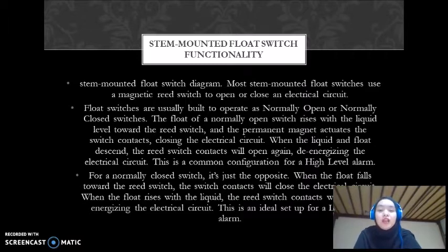For a normally closed switch, it's just the opposite. When the fluid falls towards the reed switch, the switch contact will close the electrical circuit. So that's the function of an ideal setup for a low-level alarm. The next criteria